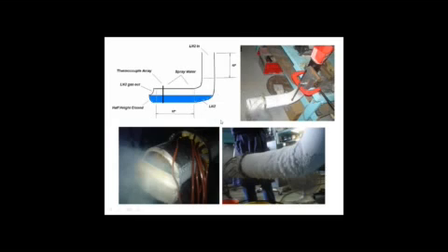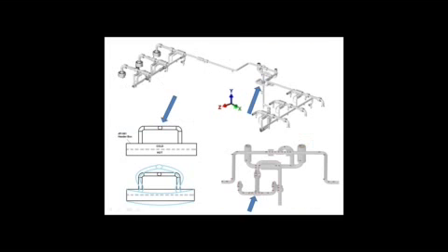The biggest condition where bowing occurs is in API 661 header boxes. The figure in the bottom shows you what happens as the box gets cold on the top and hot on the bottom. Just like a thermostat, it bows and it will collapse or crush the pipe on top. So in this case, it's important. There's oftentimes intersections at the top. The intersections at the top, D over D is 1, D over T can be a little bit high, so that can reduce the SIFs in those models.